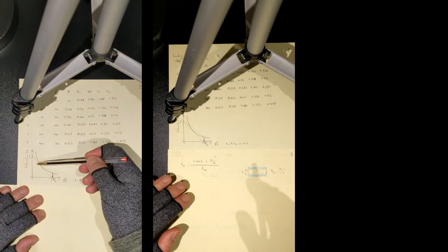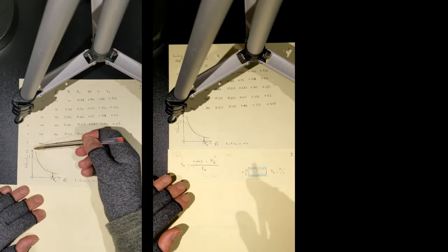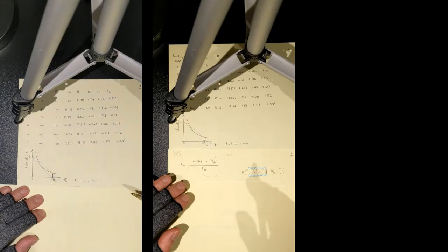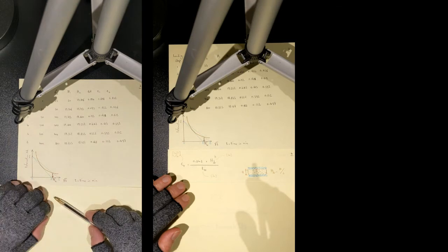So you've got this red curve, showing the variation of deformation with root square time. And you can get a parameter from this diagram. That parameter can be reported for each and any of these loading steps. Let's see what parameter I can get, and then in a few weeks' time I will tell you why this parameter is pretty important and where we can use it in our analysis.